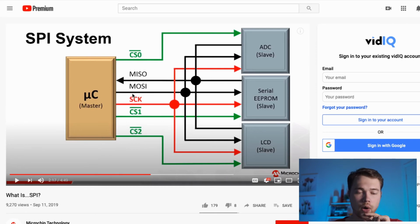Okay, perfect. Now clock, we're going to have 1 clock. This clock is split between the slaves, so all of them receive exactly the same clock signal. Same thing for MOSI and MISO. It's split and shared between the 3 slaves. So the way it's going to operate is this. The master is going to send a command to one of these slaves. It always sends the clock, and then it's going to send some signal on the MOSI wire, master out, slave in.